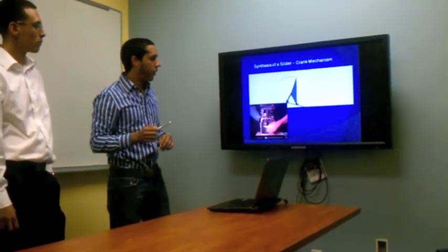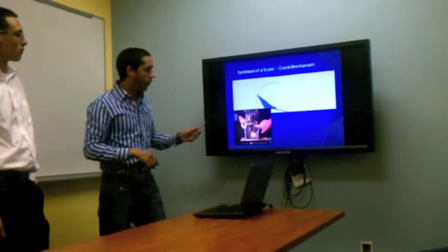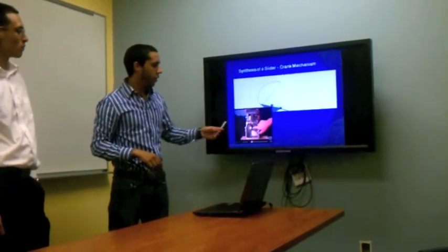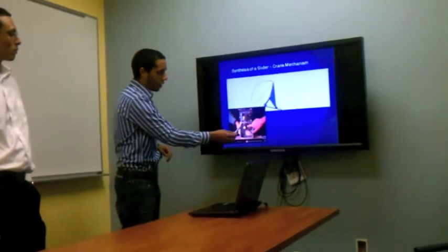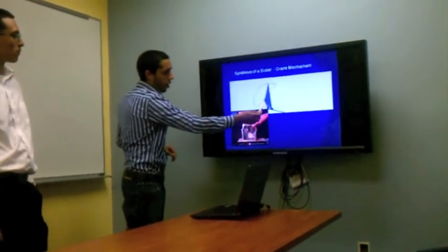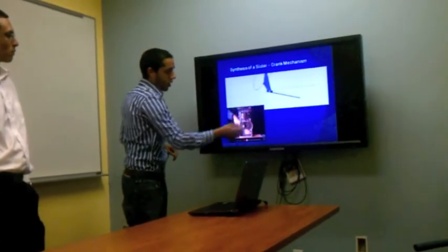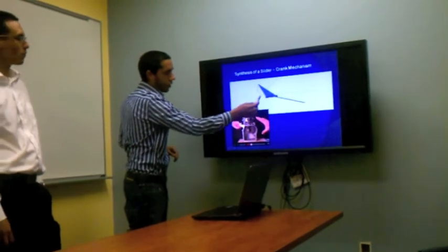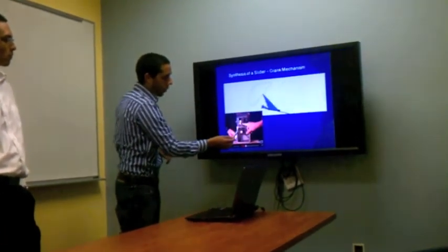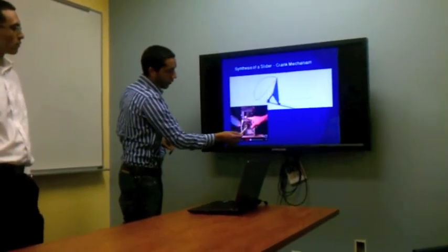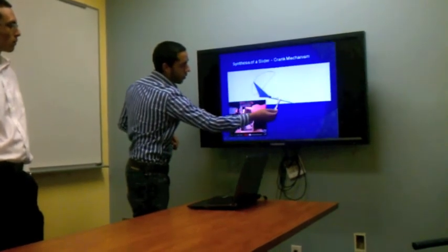A real life application for this type of system, a slider crank, would be a piston sliding through a cylinder. As you can see here, the crankshaft would be our R2, and the piston would be our sliding box. So the movement of this motor or of this link relates to this movement, and the piston will move in a straight line, just as our box is moving on this line.